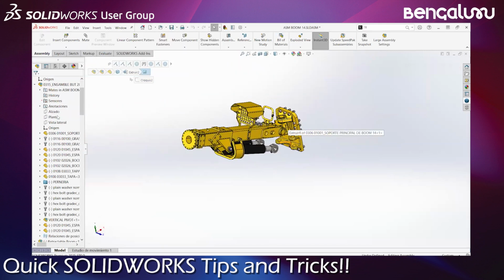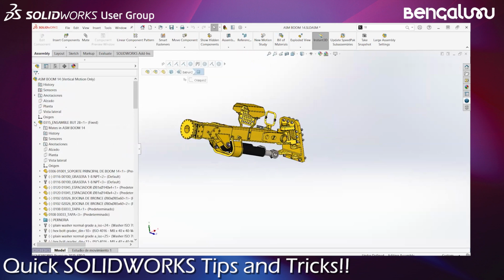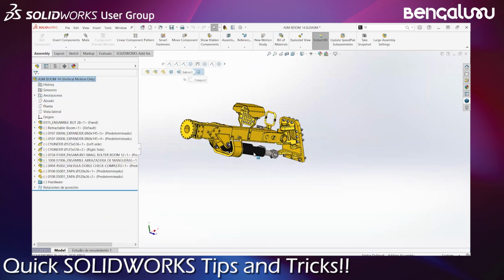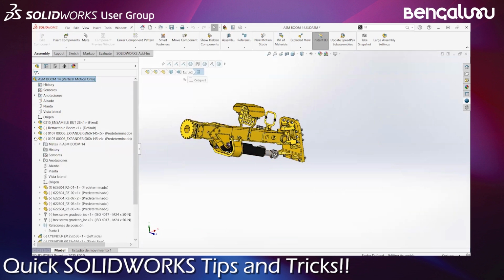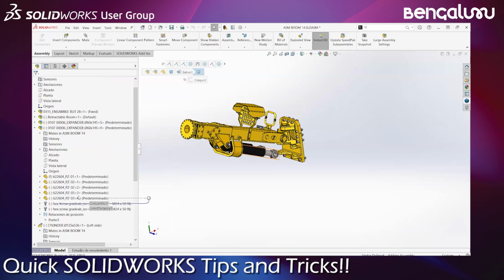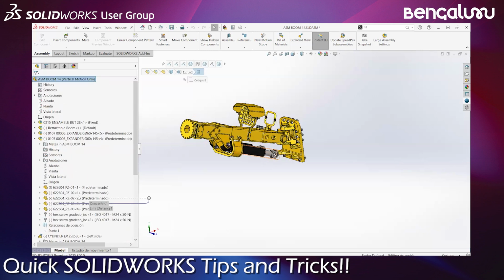Now, there's an assembly which has a lot of components and a lot of sub-assemblies, right? If you want to search for a particular component, even from the FeatureManager tree, you have to open the drop-downs and keep on searching for it, right? Is it in this assembly or where is it exactly? But if you remember the name of it, it will be easier for you to search. We have a search menu, which many users actually don't know about. So I can simply start searching for any of the models that you have, provided that you remember the name of the component.